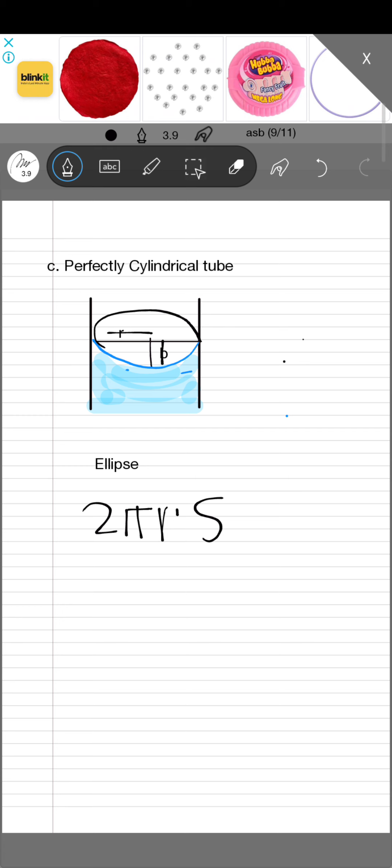That is, we are talking about the force due to surface tension, and we are equating it to the weight of the liquid raised. So again, the weight of the liquid raised can be expressed as pi r square, the area, multiplied by rho g h